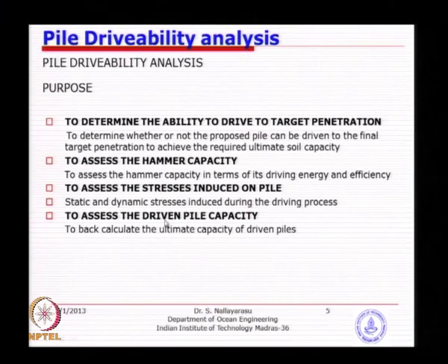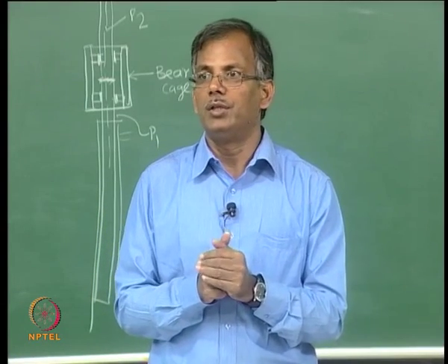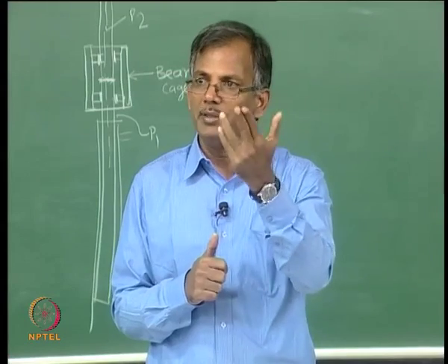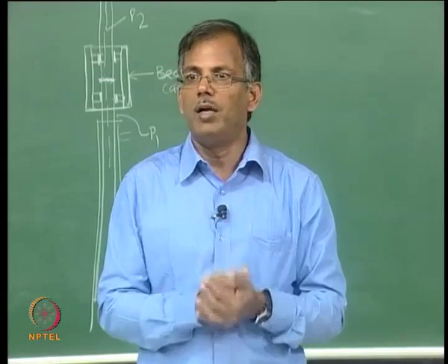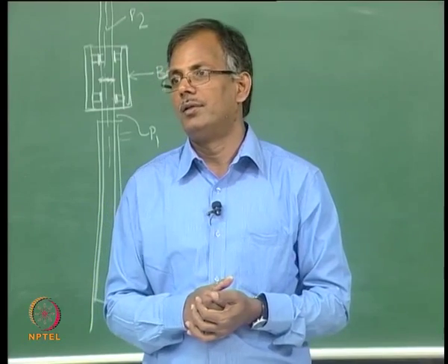I also have control over what hammer I want to use for driving. I do not want to bring in the biggest hammer in the world and place it there, is it not? So, you can bring in a hammer suitable to drive your pile to the target penetration, and that is what we want to evaluate. But with that itself, if the pile is overstressed, you can possibly change the diameter, change the wall thickness, or change the material of construction.